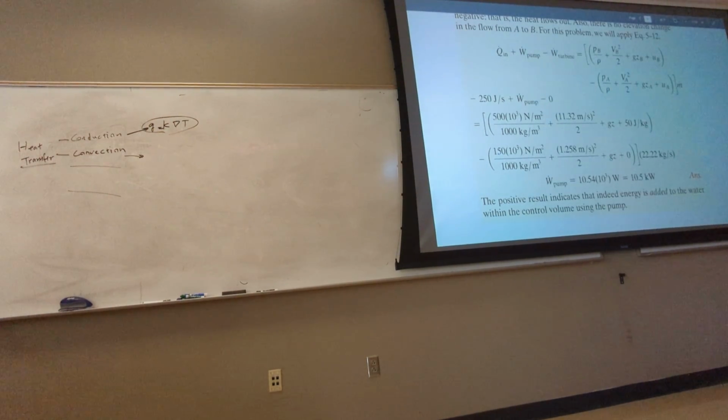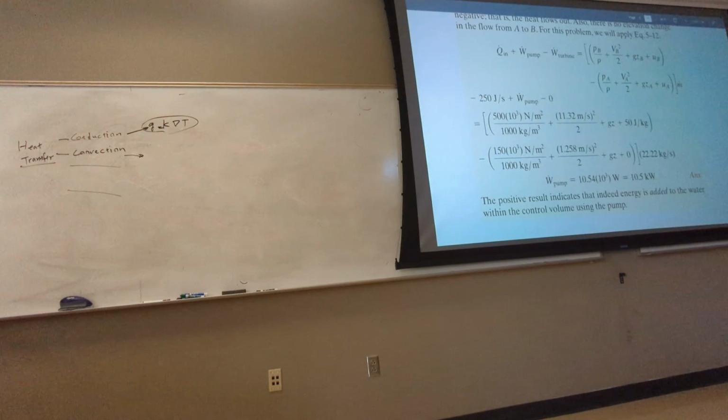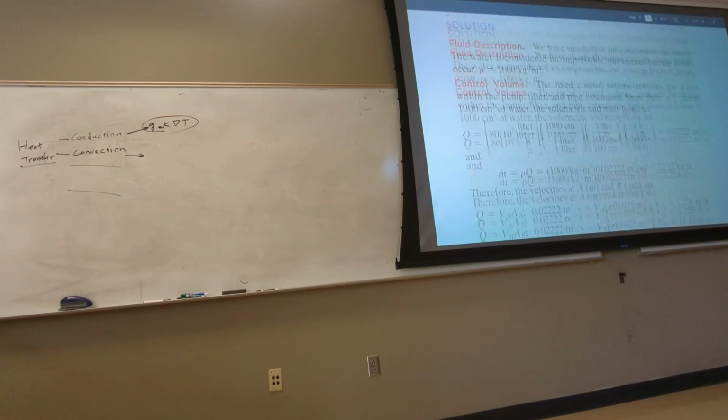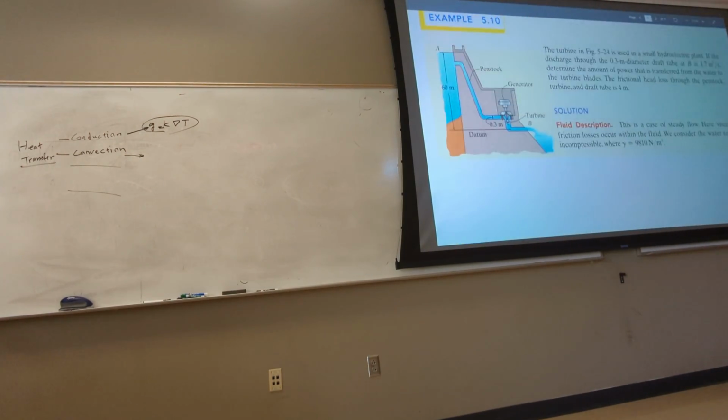And then u_B, what's the u_B? You see now, you have to take out the internal energy. You can't just say, in the previous slide, when we derived it, we added these two and said FL, this is equal to FL, fluid loss. Now, if you don't truly understand how that FL is done, you can go back and say that was actually u_B minus u_A, here in the equation.